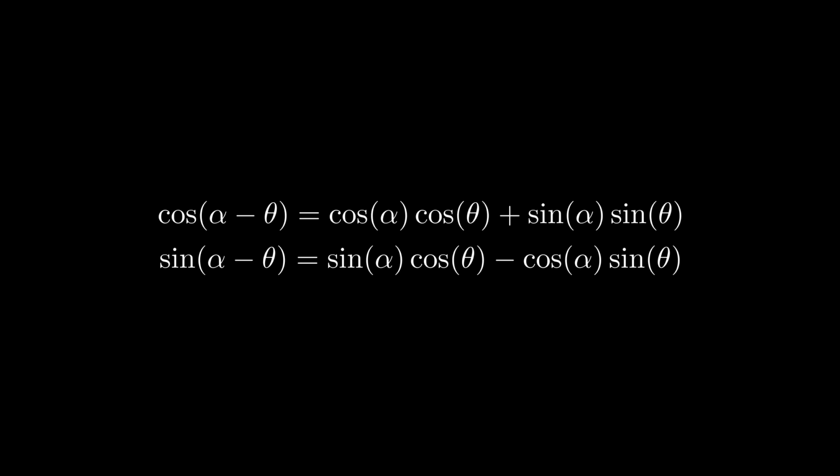Take a sec to think to yourself, do these 2 equations look familiar at all? They are in fact the angle difference formulas. The missing cosine and sine functions are those of the joystick, but they're actually embedded. Let's think of the angle that the joystick is being tilted at as alpha, and x and y as the coordinates of the joystick. No matter where the joystick goes, x and y are related to alpha. You might recognize x as the cosine of alpha and y as the sine of alpha. Therefore, we can actually go back to the elements of the transform vector and substitute cosine alpha for x and sine alpha for y. And now, we have the angle difference formulas.